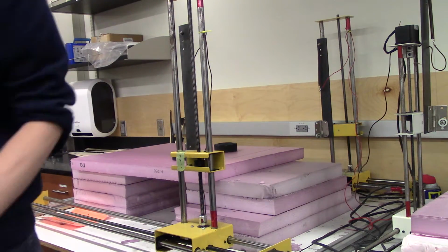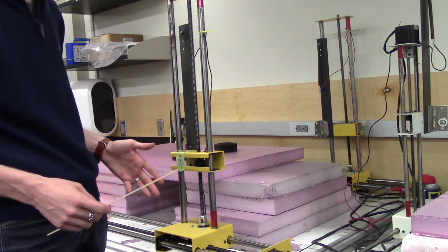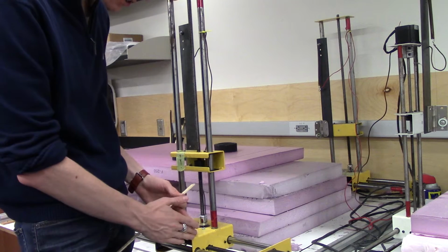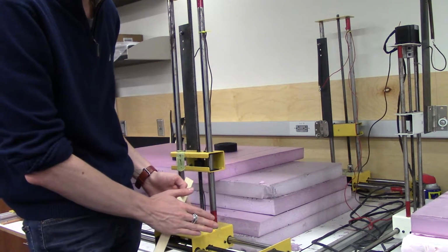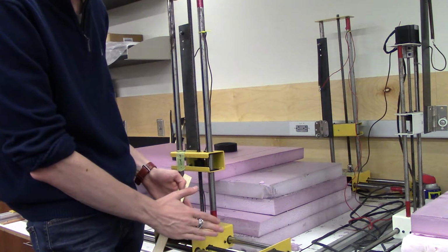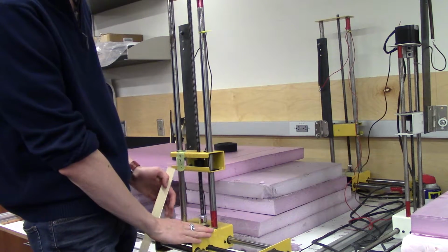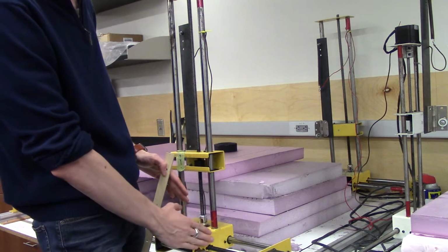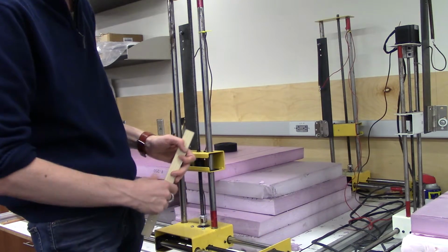If I'm going to come around here, the best way to make sure that both sides are evenly set is to measure the hard distances between the carriages themselves. So I'm going to be measuring from this yellow platform here up to the bottom of this, and the yellow over to this yellow part here.